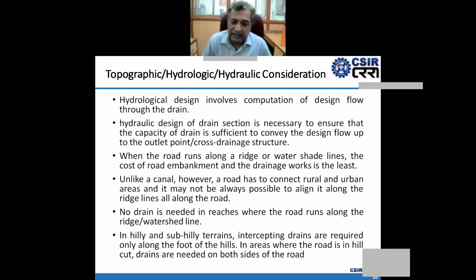No drainage is needed on ridges where the road runs along the ridge or watershed. The ridge itself is at a higher level. So in that situation, a drain is not required. In that situation, water will drain naturally.